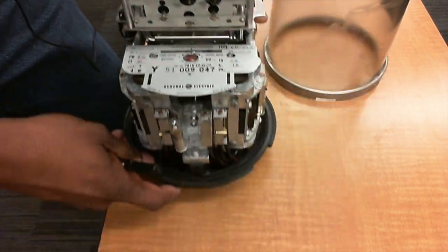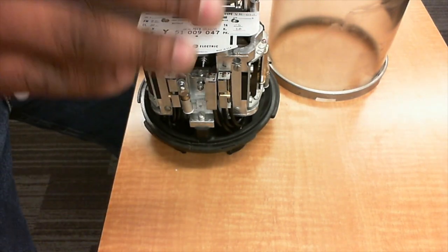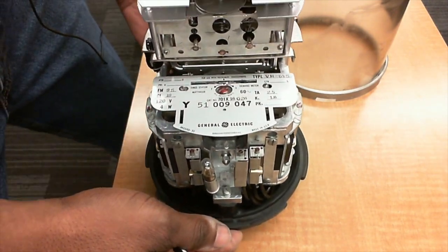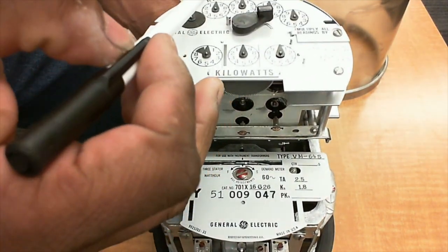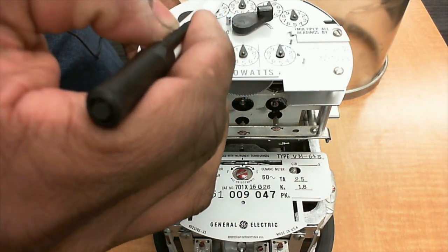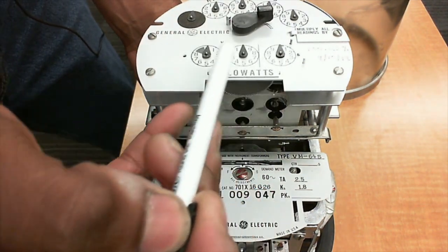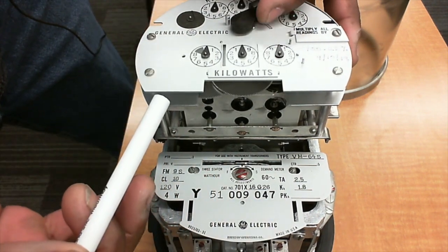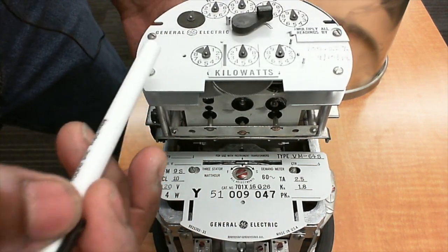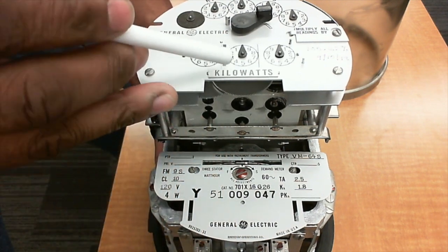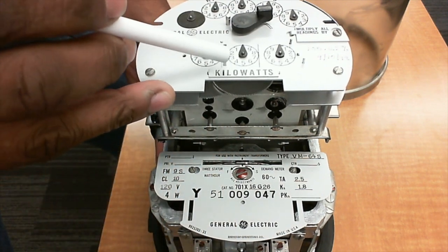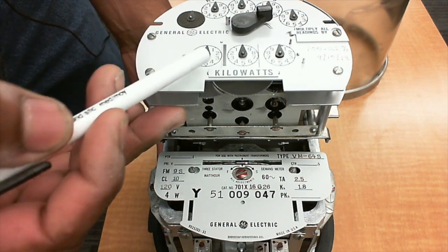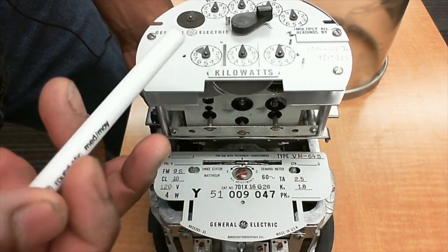The big thing I want to discuss, though, is if you do any type of demand test on an electromechanical, write down the kilowatt hours that you see here, and then write down the demand before you start doing any type of moving of this little handle here, or changing anything. And again, remember this little dot here is actually going to be a decimal place. So it's going to be a number, dot, 0, 0, whatever.